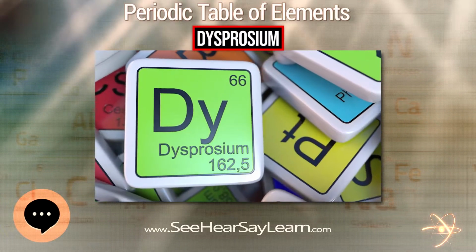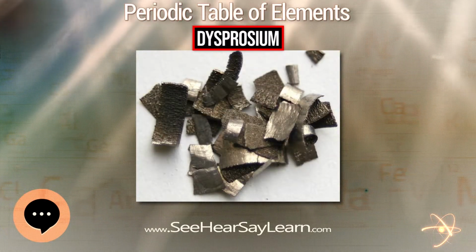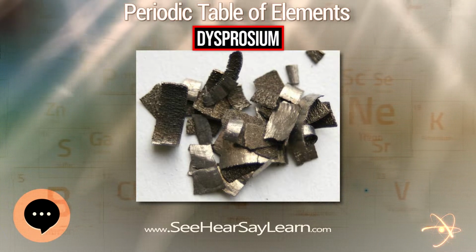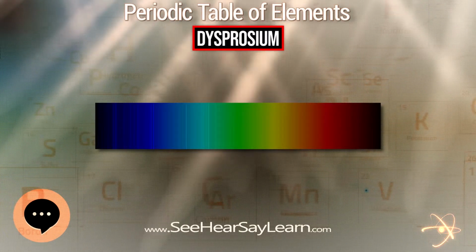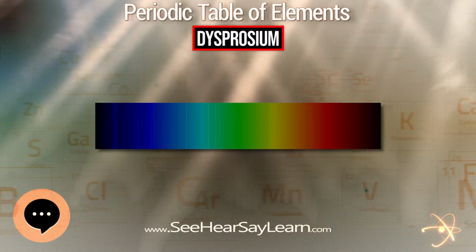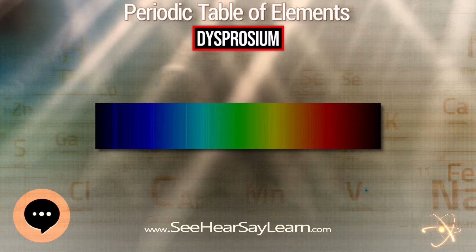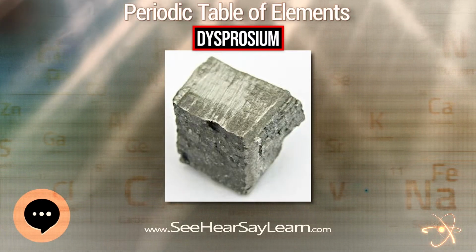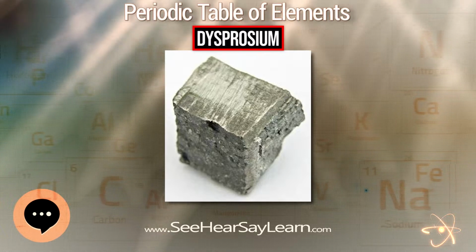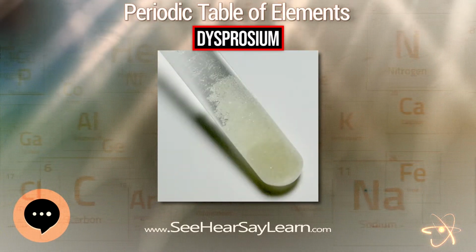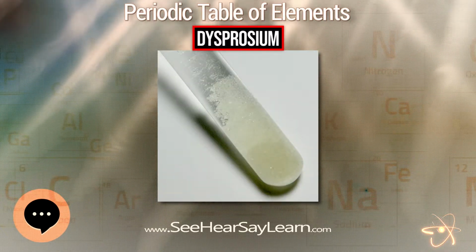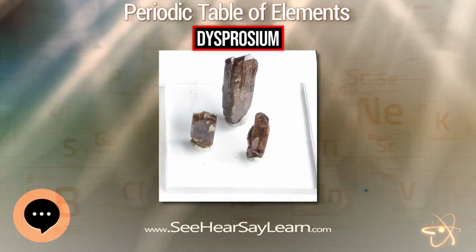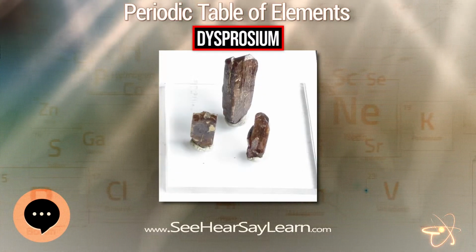Dysprosium is obtained primarily from monazite sand, a mixture of various phosphates. The metal is obtained as a byproduct in the commercial extraction of yttrium. In isolating dysprosium, most of the unwanted metals can be removed magnetically or by a flotation process. Dysprosium can then be separated from other rare earth metals by an ion exchange displacement process.